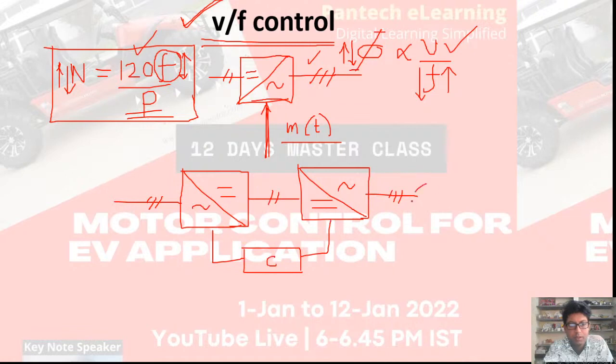So this is the controller, here is your motor. So this is a voltage controlled rectifier and this is a frequency controlled inverter. So I will make the control in such a way that based on the requirement of my RPM, to the extent I change the frequency, to that same extent I will be able to control the amplitude of the power output also. So that's why this V by F is called variable voltage variable frequency drive, or sometimes it is called 3VF, triple VF drive.